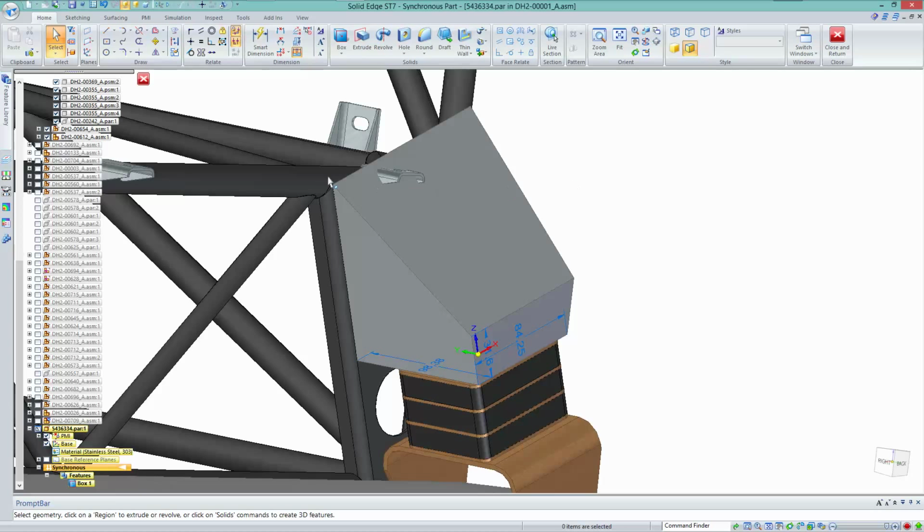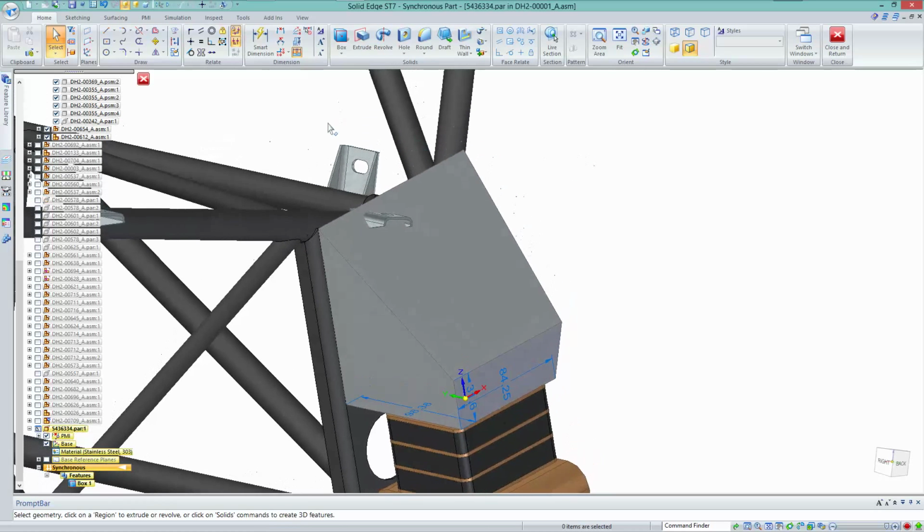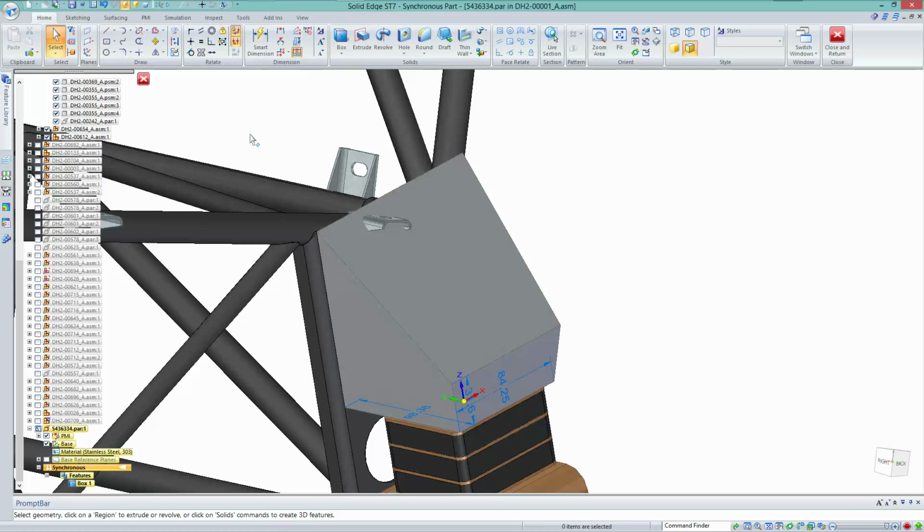I do need to lop off the top of this box, so let's see how we might do that. Again, some of the geometry in the background here, some of the geometry in some of the other parts in the assembly is going to help us achieve this. So we'll use this projector sketch. The front face on the model will help us here. The little F3 lock symbol is also useful. And it's just that edge across the top of that sheet metal component in the background that I really want to use.